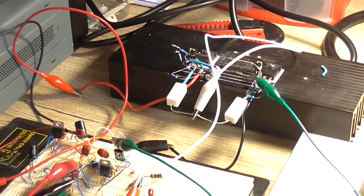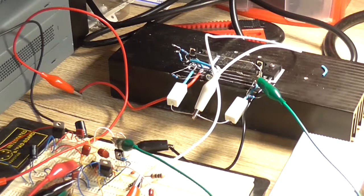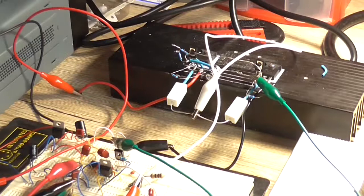But for what it is, I've got an input sensitivity now of 1.4 volt peak to peak for an output swing of 10 volt peak to peak. So yeah, you're looking at around about 3 watts. However, the results are disappointing, but I've got an output stage now to play with for other amplifier projects, even though it's connected in a Sziklai pair. I think that's going to do it for this video. The amplifier works, it just doesn't perform as well as I wanted it to.